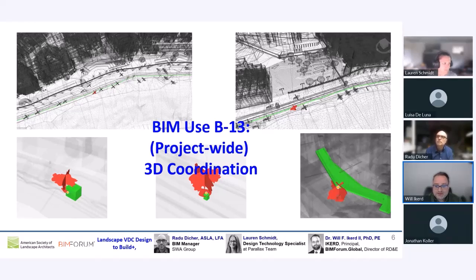So ironically, here we are, a decade into doing landscape architecture projects in BIM. And I think the software has come a long way. We're still getting challenges with some owners having US survey feet for their survey control dimensions, and all their Revit models are in international feet, and their origins are 7,000 to 7 million feet away.